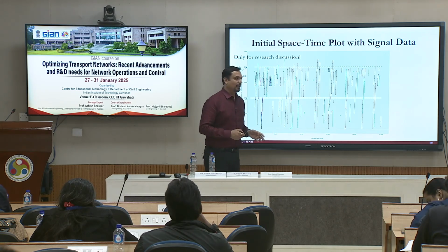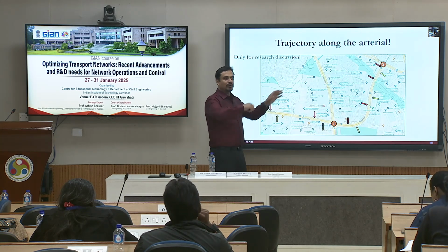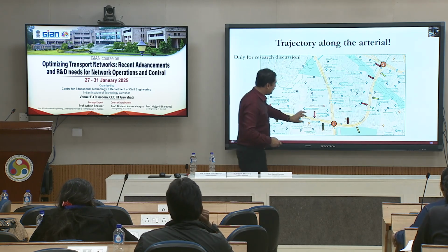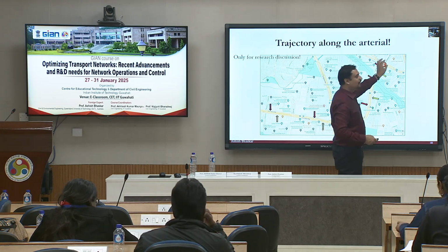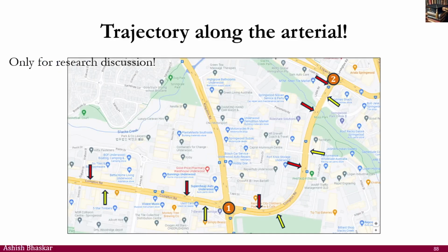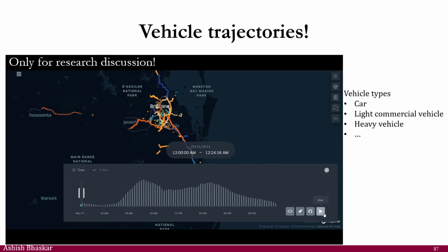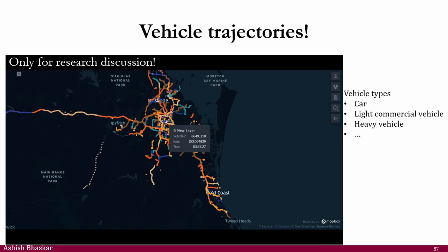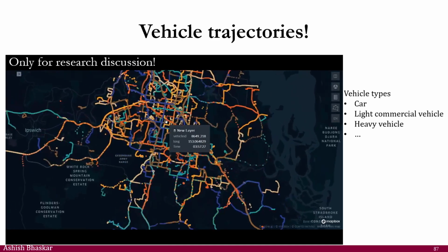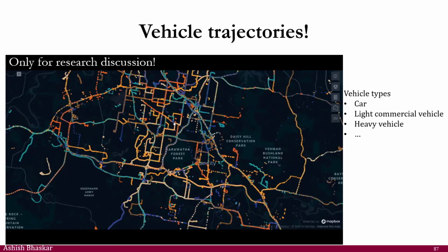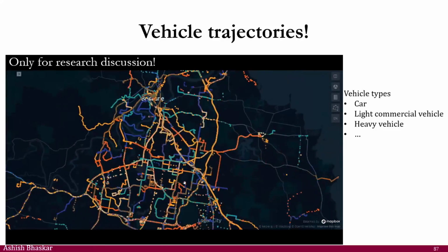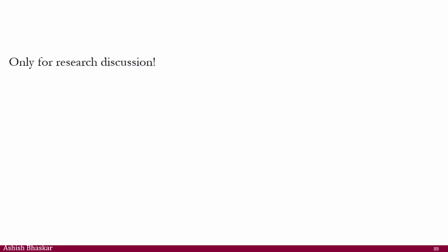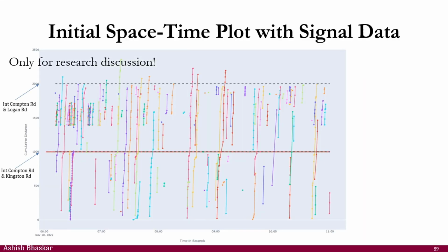No, we just filtered throughout one. That's what I said. The video I showed was everywhere, right? He just drew the buffer along this corridor and then extracted only those data points. Because what you had was GPS coordinates everywhere, XY coordinates. You get the XY trajectories for a specific trajectory. So he just opened QGIS, defined a buffer, figured out whatever data points are there, extracted them, and that was a quick analysis. Get those data points, plot them, and connect the ones having the same IDs so that I can see them as a trajectory.